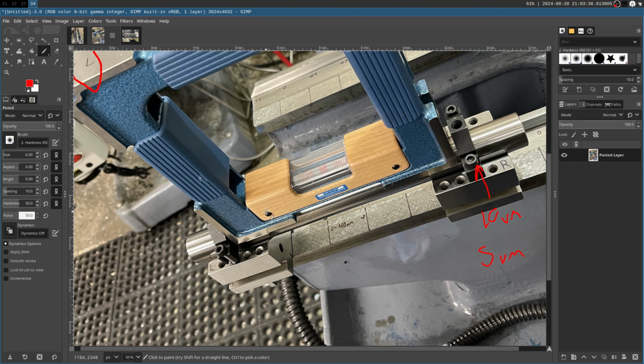So that means that with this process, I should be able to accurately and consistently measure things to basically the factory specifications. In reality, since this lathe is 80 years old, it has significant wear, and thus we are still in the 50 micron level, and I would say we probably have approximately 10x more precision than what we're measuring. So we should be able to form a relatively good image of the bed of this lathe with this current instrumentation.